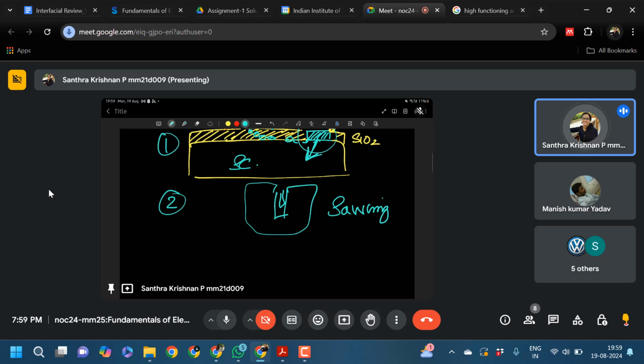Cutting wafers can be sawing, scribing, laser cutting, or mechanical sawing. Basically, you use a saw, like a wood saw. Similar to that, there will be a saw, and using that saw, you cut. Another is laser cutting, using a laser beam. Another is using a diamond: according to your wafer material, you use a pen-like scriber, mark the edges, and then cut. After scribing, you break it in the opposite direction, just like we cut glass in the laboratory. The same way you can cut a wafer. So these are the different methods of cutting.